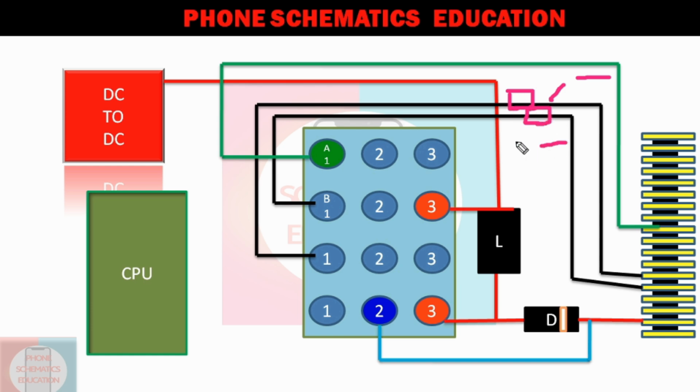Now, if you measure a diode value on the multimeter in diode mode, suppose 600 on both lines, that means this line is connected properly with the IC, or in some cases this line gives a beep in diode mode. If you have a multimeter, use it. Otherwise, you will rarely see a problem in this line. You can just measure whether this line is connected or not. That's it for the cathode.